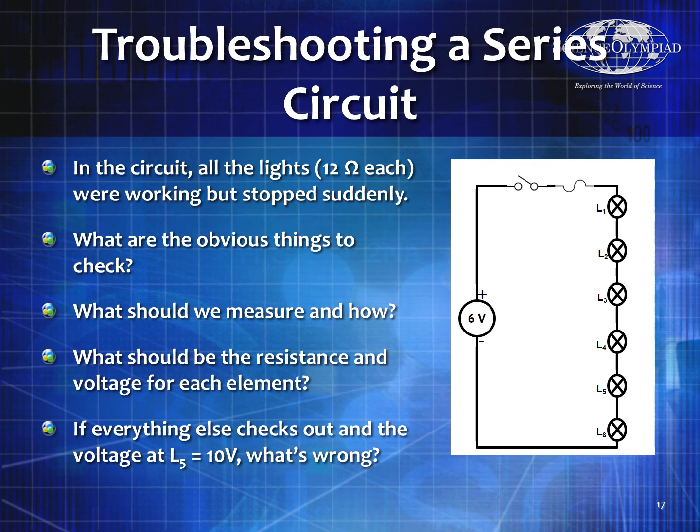Okay, well, physically, the fuse looks like it's in place. Physically, the fuse does not look like it's burnt out. Okay, I measure the voltage across there. The voltage is 0, so that means it's acting as a short, so it's not going to be the fuse.